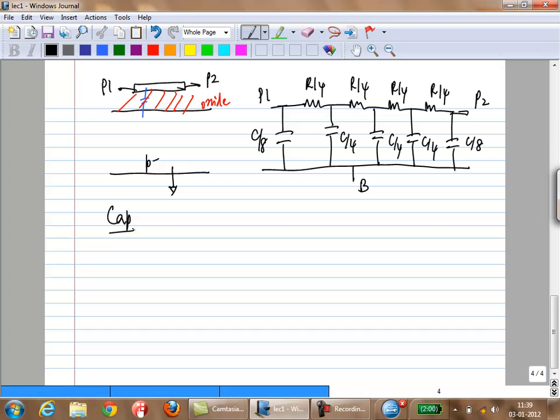How about capacitors? Normally you have two kinds. This is the standard passive parallel plate capacitor. You have two metals, and you have an insulator in between them. This insulator could be the standard oxide. It could be some special material, what are called high K materials, which have very high dielectric coefficients.